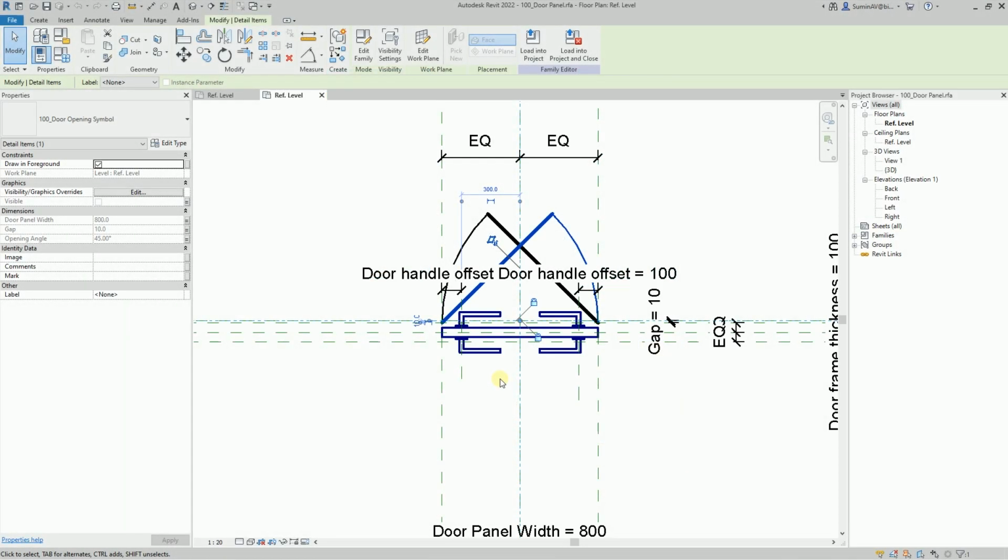Let's create another door panel that will be slightly different from the already created one. If we want to replace one nesting with another within the parent family, then each of these nested families must have the same set of parameters. I mean only those ones that are related to the parent family parameters.